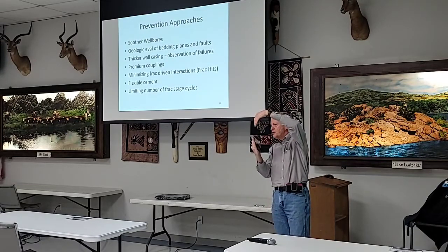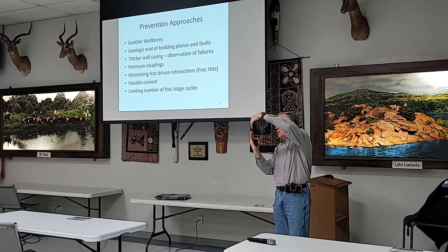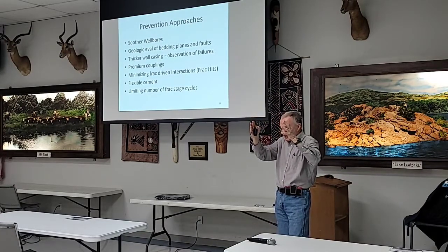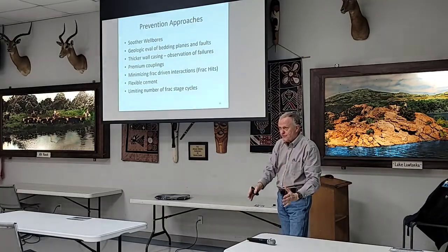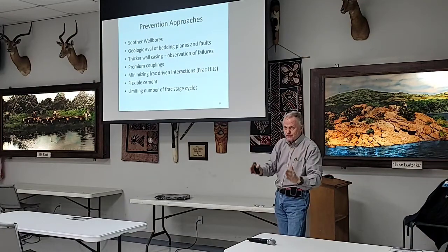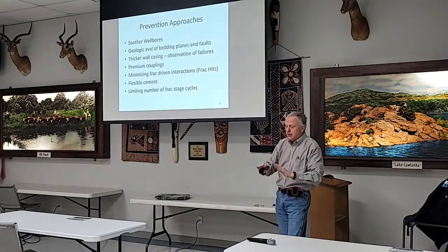That's where those pipes are coming together. If they don't end up touching each other, you've got a little gap. Well, you pump liquid by that with sand in it, you'll create an eddy current. You'll destroy your boundary layers, and it will take 2 or 3 joints before that boundary layer reforms smoothly and you get your flow lines going straight.